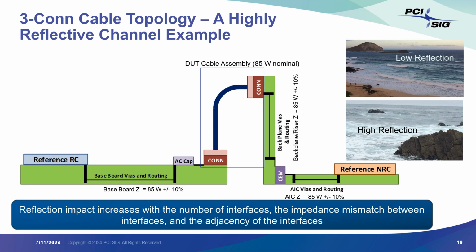And it's going to reflect back and forth between multiple of those interfaces. And those reflections to a receiver are basically noise. And those usual same-impedance interface changes also cause opportunities for crosstalk, and that also appears as noise in our final receiver. So we need to control them.